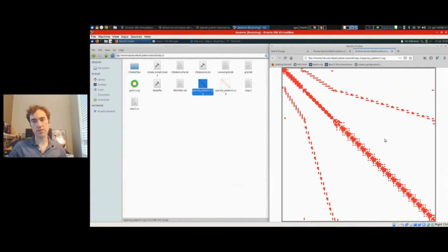There's other stuff that we generate, and I will quickly show you maybe the first one. This is a sparsity pattern. So for this problem, I distribute degrees of freedom and then decide for each coupling phi_i, phi_j, whether there's an entry in my matrix. For those of you who know finite elements, you know how finite element matrices look. Only if phi_i and phi_j are close enough to each other that the support functions share support, then you actually have a non-zero entry. So in this example, this is how the sparsity pattern looks, for example, I think for a linear finite element, but I have to double check. So this is all that this tutorial does, and I will quickly show you how it works.